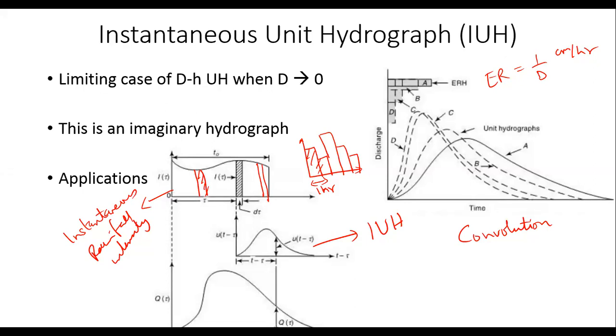What we meant by those terminology was that any given unit hydrograph for a given catchment or a given watershed has a correspondence to the duration of the rainfall event, right? So if I have, for instance, a 2-hour unit hydrograph, that corresponds to an excess rainfall event of 1 centimeter happening over a duration of 2 hours, right?